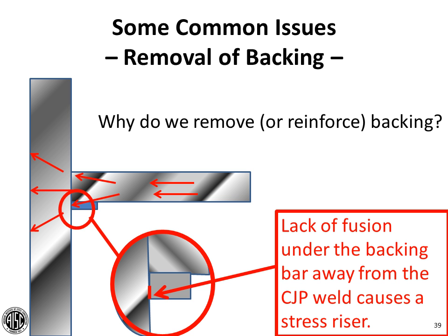Next, I'm going to talk about removal of backing. So this one actually comes up a lot from fabricators and erectors, more so even than from engineers, where a fabricator or erector believes that all backing needs to be removed as soon as they're having to meet AISC 341, the seismic provisions. And that's not true at all. In the majority of the cases still, you can probably leave your backing in place. In some cases you're going to need to reinforce it, and we'll talk about that in a minute.